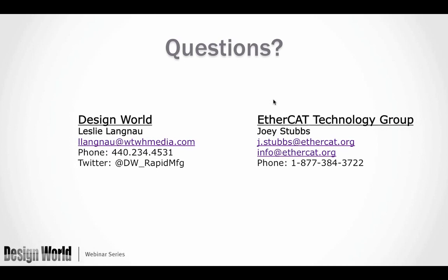So it's called a mailbox in the EtherCAT world, and you can go to the ethercat.org website, and there's a technology overview which talks about that in probably more detail than I could fit in the rest of our Q&A session here. But in the typical implementation of EtherCAT, you have leftover bandwidth. So we can use it for this acyclic communication while keeping our process data frames very regular, instead of having to set aside a big chunk of time just in case we have acyclic data.